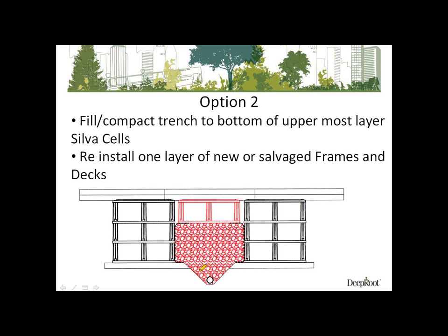Another version of that same thing is get your soil compacted below the Silva Cell area. Make sure you have your base reestablished. Only here though, taking off on our utility bridging detail that we showed earlier on, you would put geogrid on either side to contain the compactable soil here, or it can be clear stone, whatever your foundation material is.